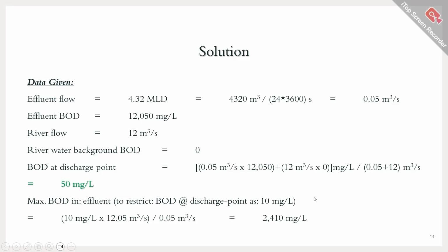After that mixing, again these 5 zones will form. So the microbes that are present inside the water will, with the help of the dissolved oxygen, be able to degrade the BOD to the 0 level again. So that 5 zones formation graph that we just showed in the earlier MCQ, this is the aftermath, right?